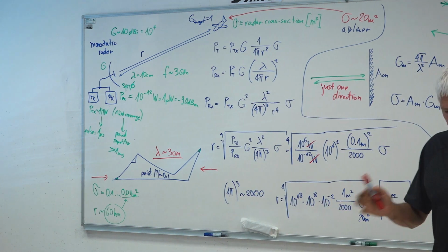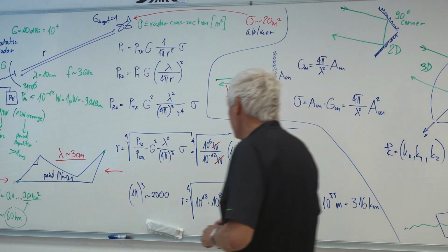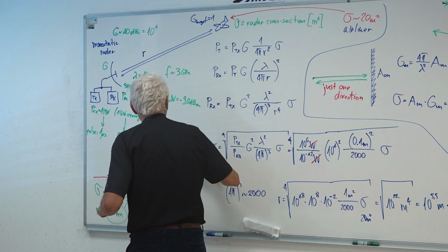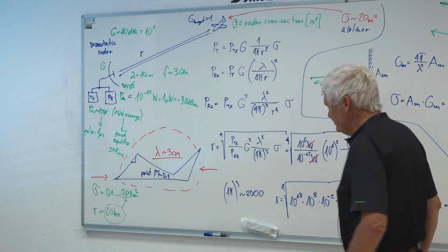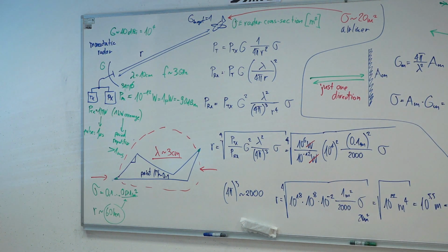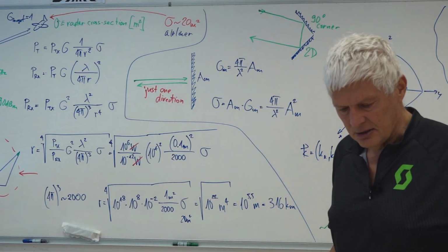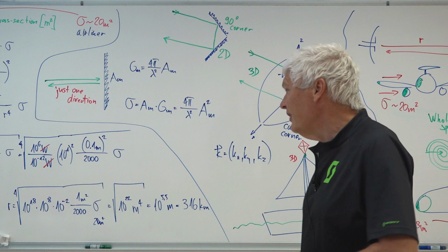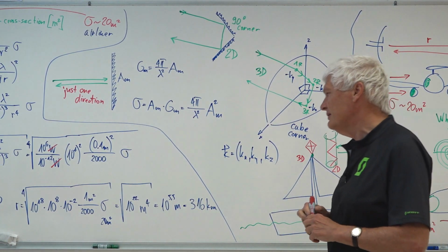If you look at this aircraft at longer wavelength, your sphere becomes like this. At longer wavelengths, you don't see the shape of the aircraft, you see the whole aircraft acting as a single sphere. And at longer wavelengths, such an aircraft has a much larger radar cross-section. So how to shoot down such an aircraft? First, you have to detect the aircraft at much longer wavelength.